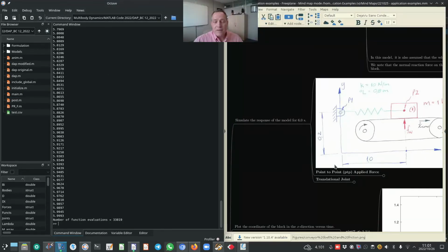Okay, so it's clear it took quite a while to run the simulation, and I just want to point out that the time it takes for the simulation to run is not affected by the reporting time step that we specified. We've specified quite a small reporting time step of 0,01 seconds or 10 milliseconds, but if you run the simulation with a larger reporting time step, for example 0,1 seconds, the simulation takes the same length of time to run.